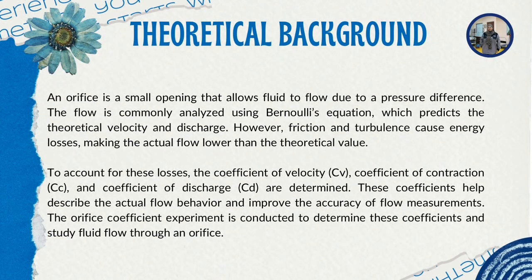Theoretical background. An orifice is a small opening that allows fluid to flow due to a pressure difference. The flow is commonly analyzed using the Bernoulli equation, which predicts the theoretical velocity and discharge. However, friction and turbulence cause energy losses, making the actual flow lower than the theoretical value.